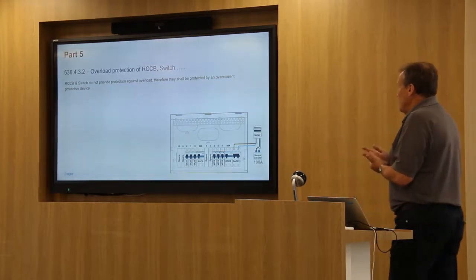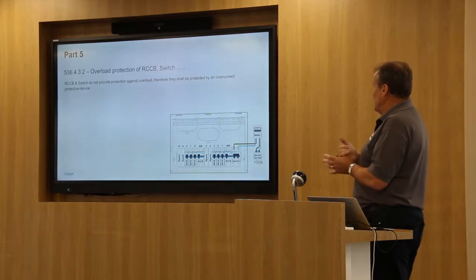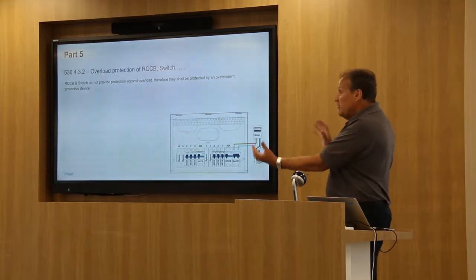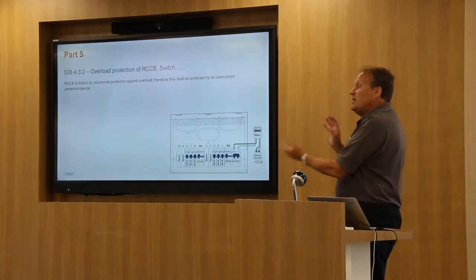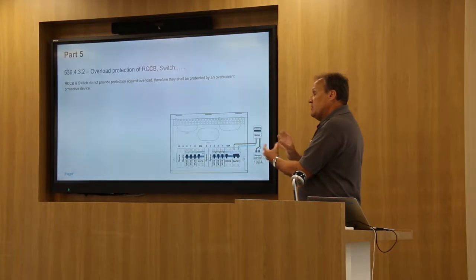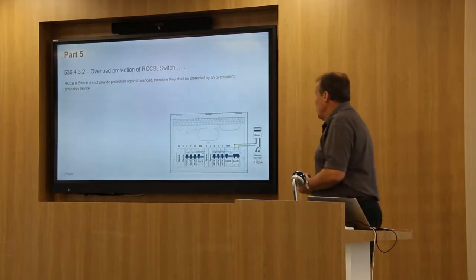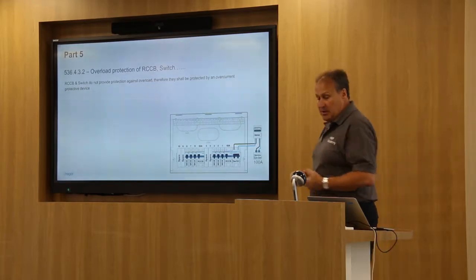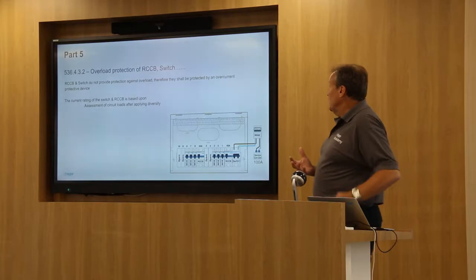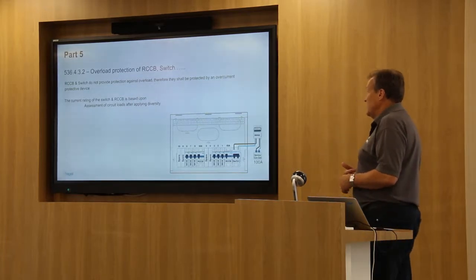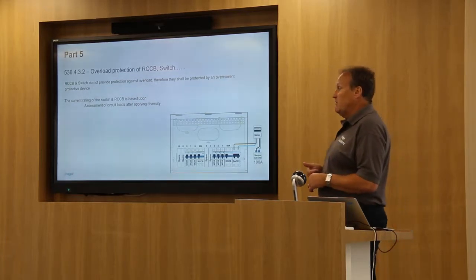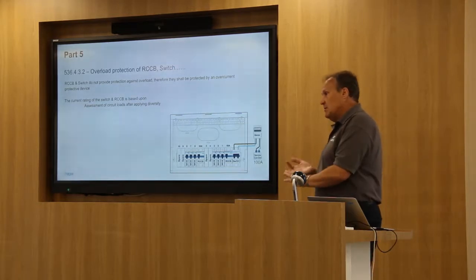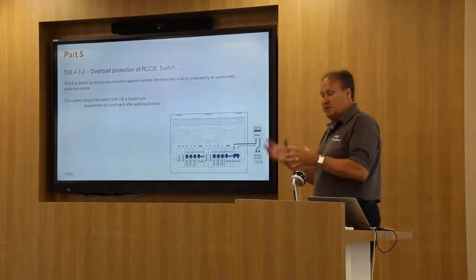Okay, so in the consumer unit there, you can see we have a 100 amp supply to the property maybe. We may have a 100 amp consumer unit, but inside, quite usually, and for the majority of the time, certainly from the products we sell, the majority of the products are only 63 amp RCCBs in the consumer unit, which has been fine because the current rating of that switch or RCCB is usually based on the application of diversity, meaning you won't be using all the circuits to their full capacity at any one time, which is a sensible design process.